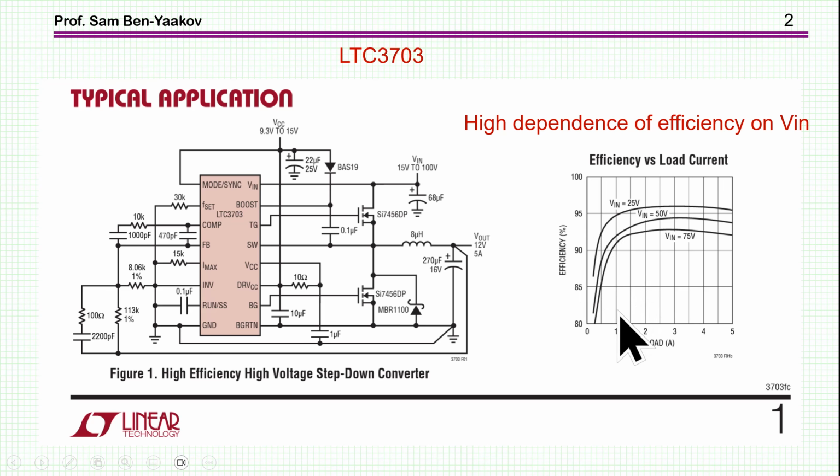Now in some cases the efficiency at low power is important. This is because, first of all, power supplies do not run at nominal power all the time. Many times they are running at a lower power level. Especially if we are talking about an arrangement of redundant power supplies, in which we have parallel power supplies working so that if one fails then the others take over. In this case, all of them will be working at lower power in the normal mode. So in some cases, higher efficiency at low power is important.